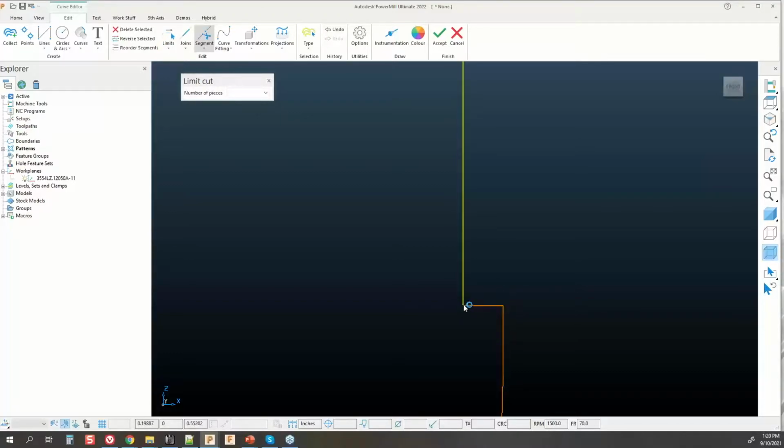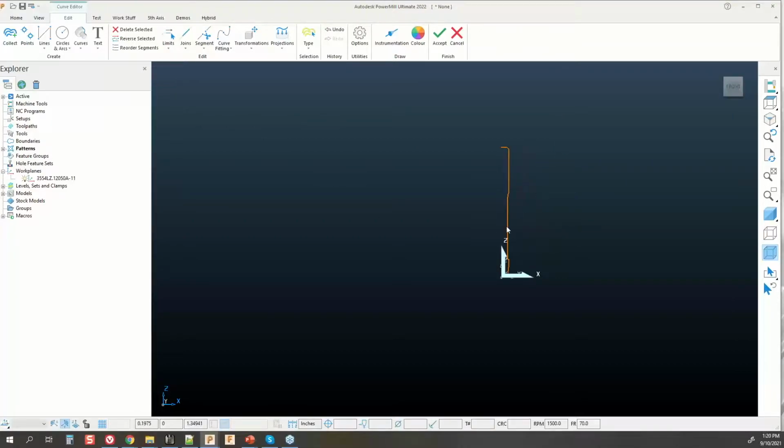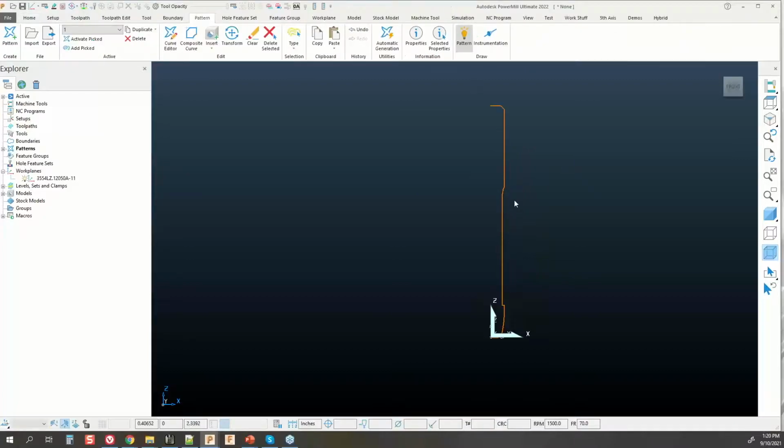I'm going to pull the cutting data in a different fashion here. We'll do it two different ways. We'll do the form tool, which is going to use this cutting data here for the spun profile. And we're also going to do the barrel tipped tool with this cutter. Once I have those segments separated here, we can go in and start creating our tool.